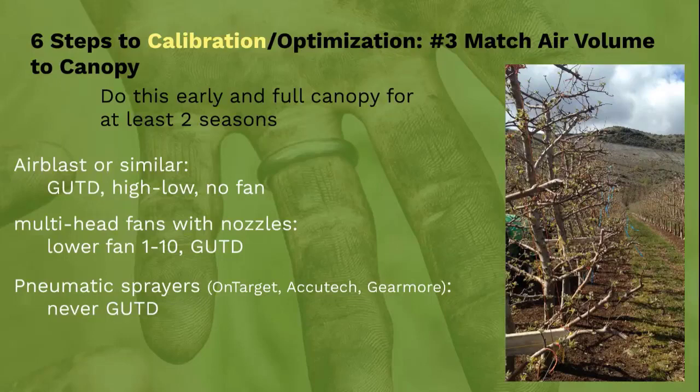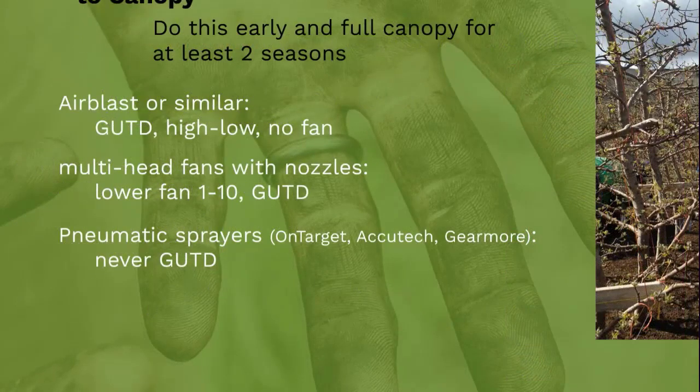But when you throttle down, you reduce the speed again, but this also reduces the rotations of the PTO and therefore the rotations of the fan and the volume of the air from the fan. As an added bonus, it saves on fuel. So other options for these sprayers, and you can see that I put gear up, throttle down as a second